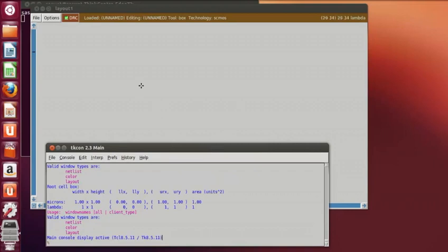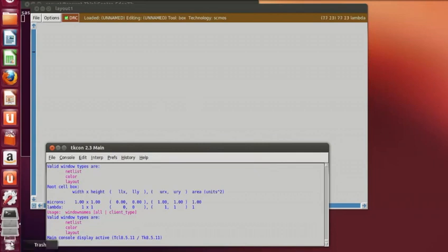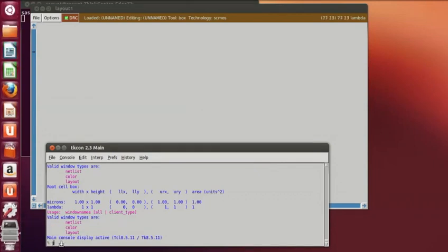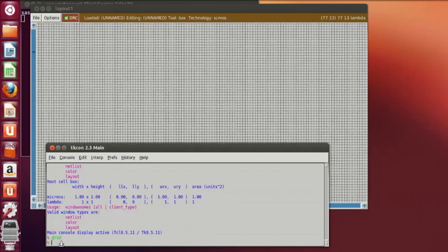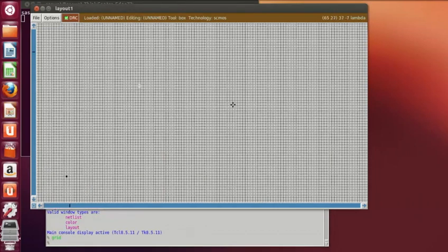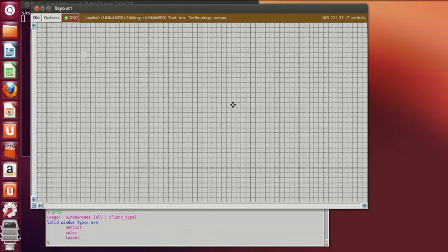So at first we will see the layout by using the commands. In order to grid in, type grid, press enter. If you want to zoom in, press Z. Now in order to draw the layout of a 2-input XNOR gate, we need 2 inverters and 2 transmission gates. Since we are drawing the XNOR gate using transmission gate, we need 4 PMOS and 4 NMOS.